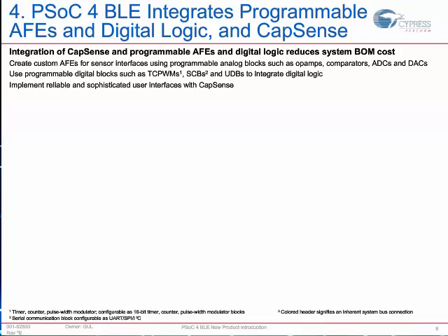And just like I showed you in the first slide with PSoC Creator, you can drag and drop those op-amps, those comparators, those ADCs, and those muxes onto your schematic and wire them up in a way such that they represent that circuit that you would make outside of the chip or from another IC that you would buy. You could implement that entire analog front end for a heart rate monitor sensor inside a PSoC, and all it would need on the outside would be the actual electrodes and maybe a few passive components like a resistor and so on to attach to the chip.